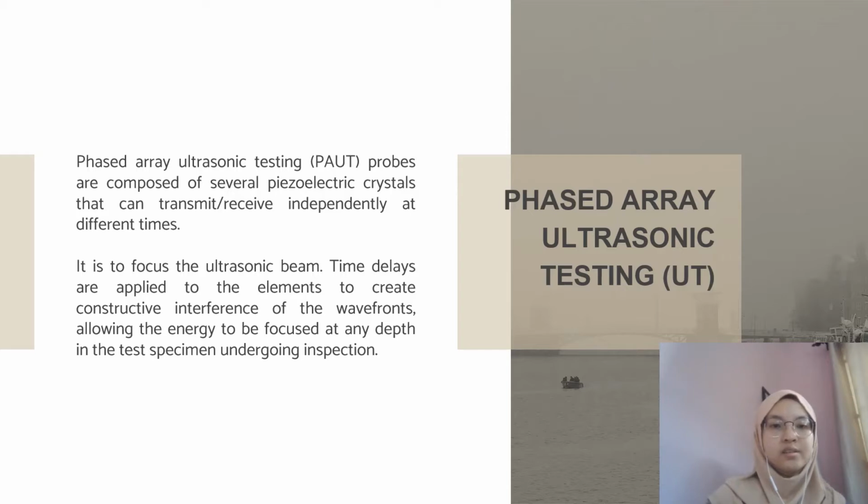Phased array ultrasonic testing, which is PAUT, probes are composed of several piezoelectric crystals that can transmit or receive independently at different times. It is to focus the ultrasonic beam. The time delays are applied to the elements to create constructive interference of the wavefront, allowing the energy to be focused at any depth in the test specimen undergoing inspection.